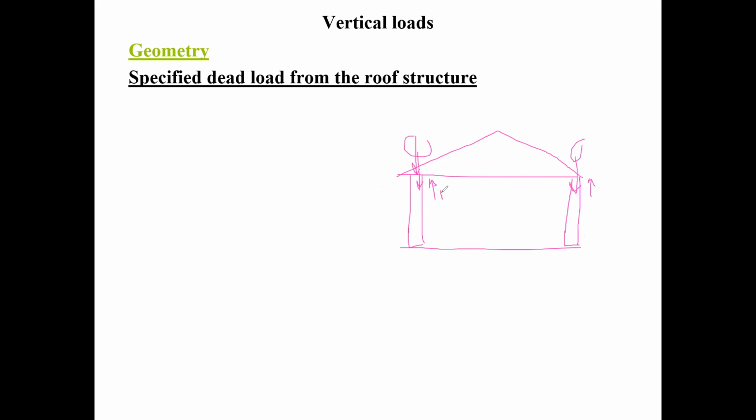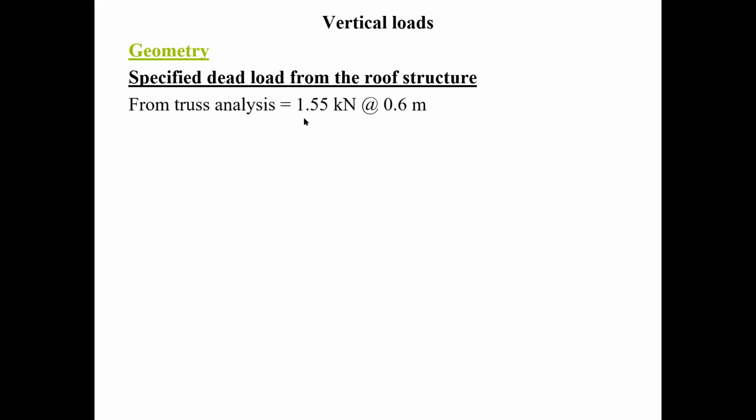So the Ry on this side and the Ry on that side will give me my P. In other words, I would use the specified force, and I said, why don't I just go and get those values from ADA? Basically, from the truss analysis, I looked at the resultants of just the dead and the superimposed dead.